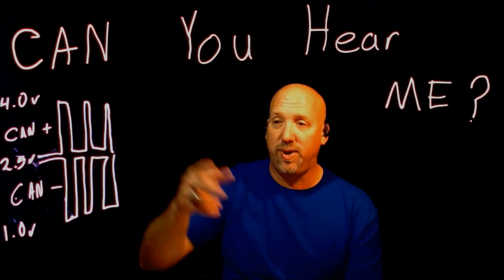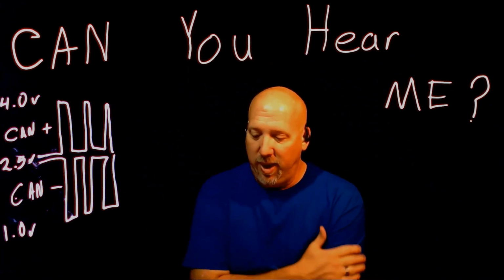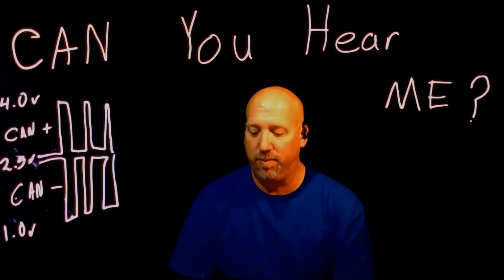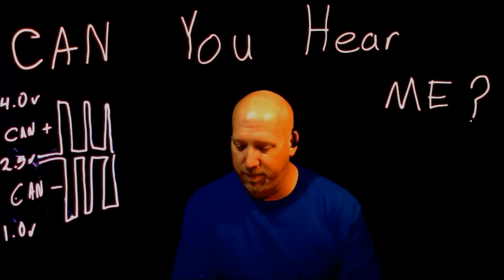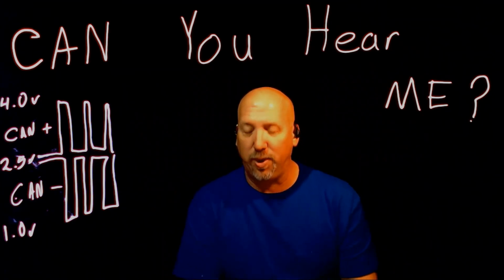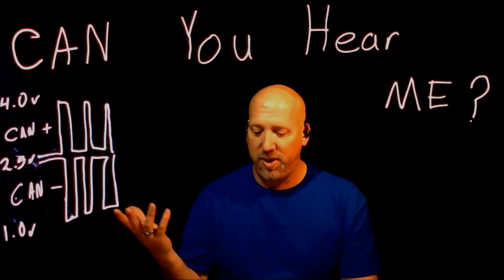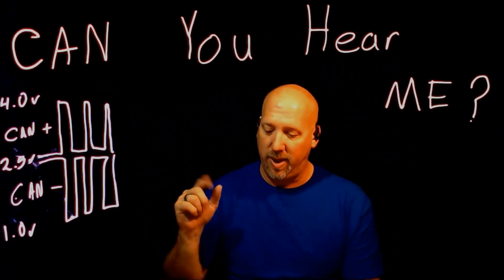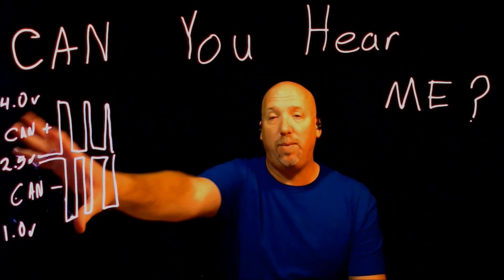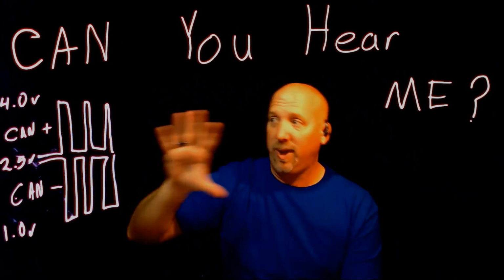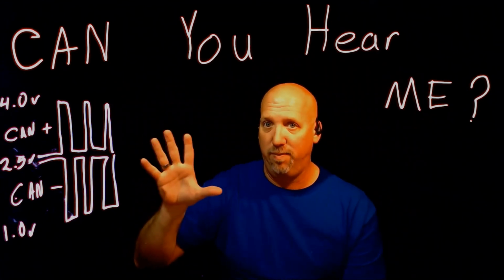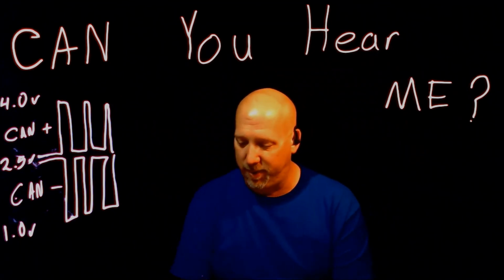However, the two circuits are designed to stabilize each other, so any open in either circuit may cause some message corruption. Your data has been corrupted, causing erratic system operation or intermittent codes, in addition to open CAN circuit codes that will be present. If you have a problem in your CAN bus system, such as an open circuit, it's going to give you a network code coming up here.